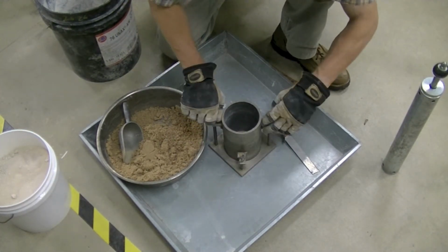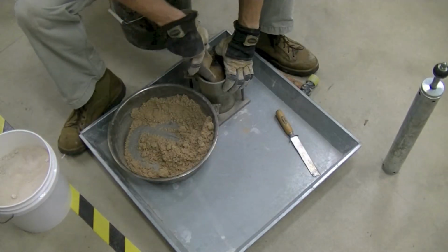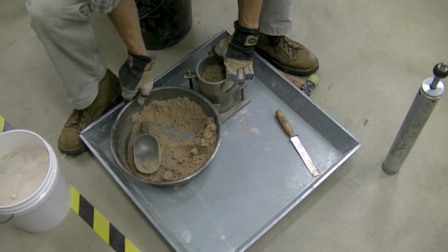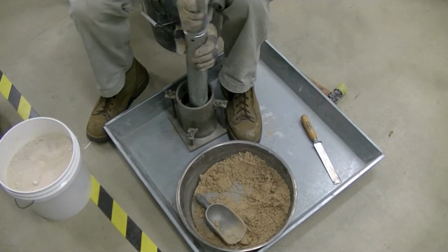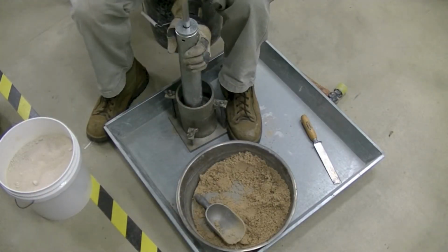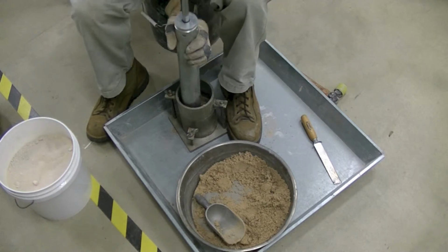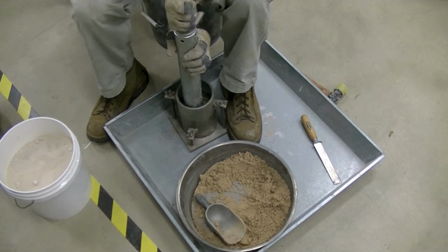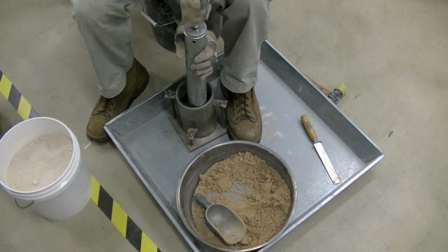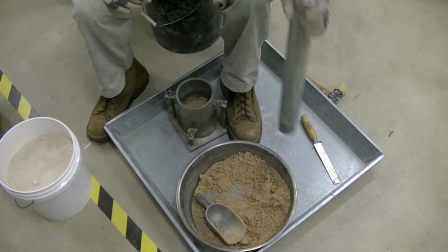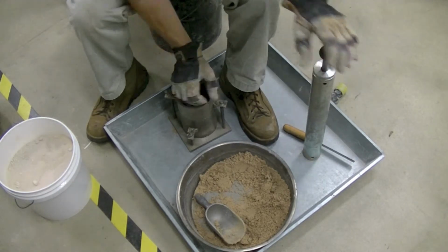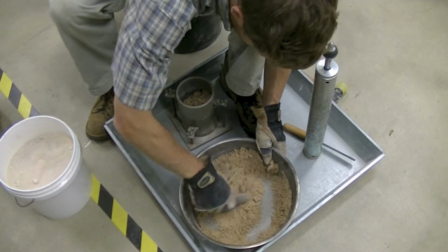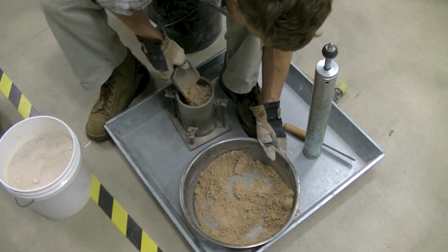For the points that are dry of optimum, notice that the soil does not easily compact and hammering seems to not do a lot. For the points close to the optimum moisture content, notice that the soil compacts easily under hammer strokes. For the points wet of optimum, notice how the hammer sinks and sticks into the sample, making it difficult to remove. Be sure and be consistent for all points and allow sufficient time for moisture content samples to dry.